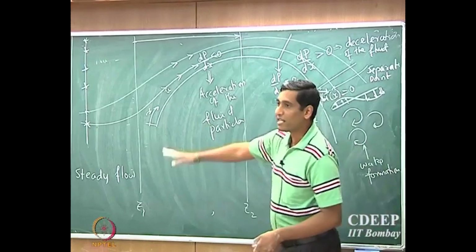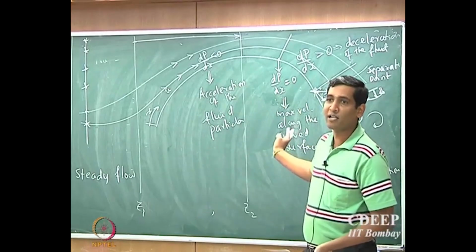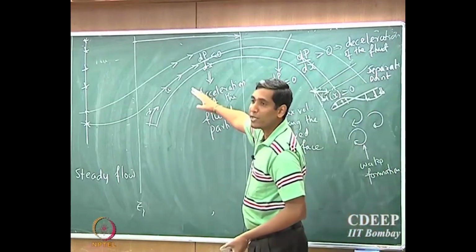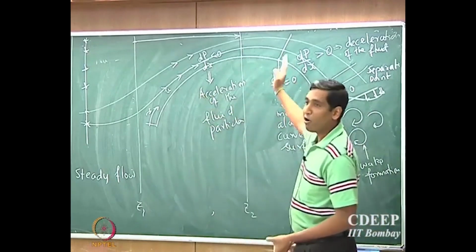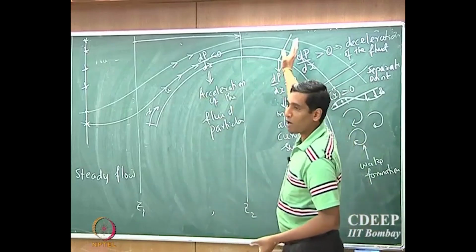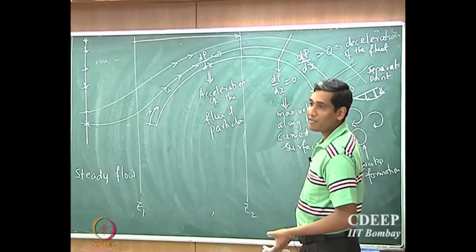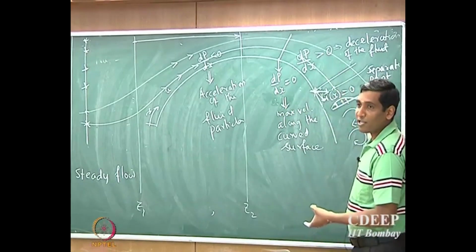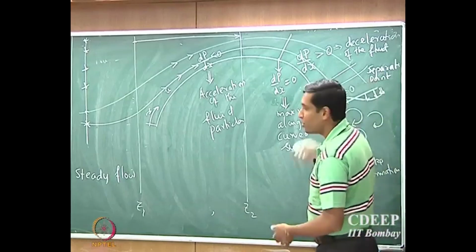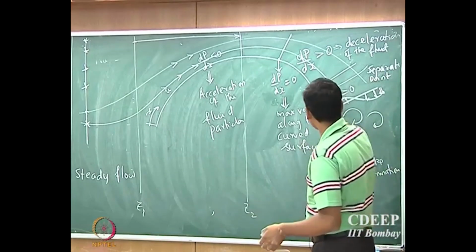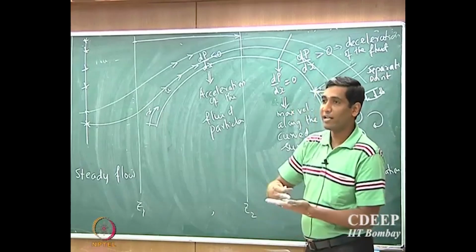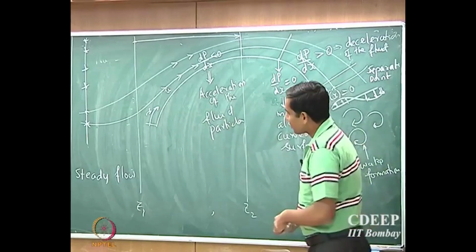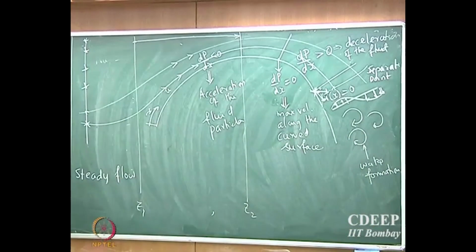Okay. So there is a series of interesting events that occur to these fluid particles flowing past the cylinder. First it experiences an acceleration, and then it's not able to sustain the acceleration, so the velocity goes to a maximum and starts falling down. There's an adverse pressure gradient in order to catch up with the rest of the fluid stream, and it's not able to manage it, and therefore the velocity comes to 0, it leaves the surface, and then it starts circulating. That's exactly what happens in this location here.